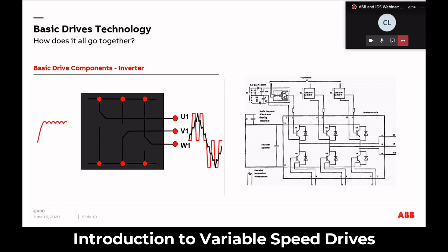But to be honest, again, like with the DC link, I've kind of over exaggerated, because in reality you would not get something as rough as that. It'd probably be something a lot smoother, but you'll see some minor jagged edges at least anyway. And again, as a result of all this, it all varies on what's on the output of there, but also what the overall length of those cables are going to be as well.